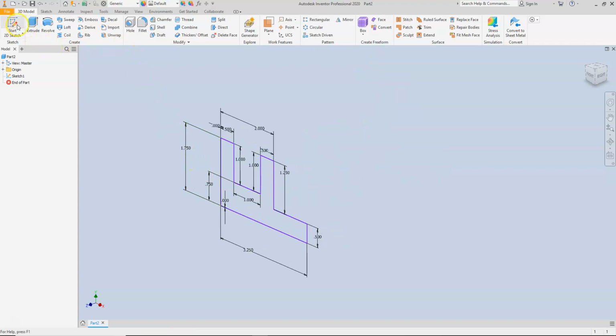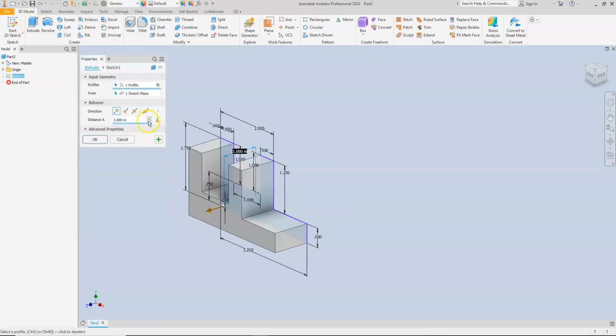Now, the extrusion that we're going to use today, just want you to take a look. We do have several different types or behaviors of the extrusions, and up to this point, we've been flip-flopping between what side of the work plane we want to extrude to. So today, the textbook introduces using the symmetric extrude. This one allows you to split the difference symmetrically between the planes.